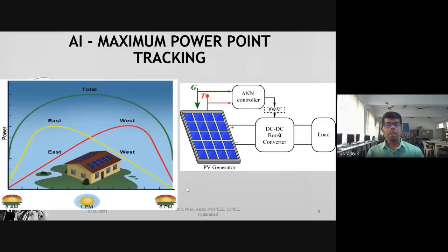That is how you maintain the efficiency at the battery. Here in the PV generator panel, you can take the temperature of the panel, what generation is happening, and what angle it is tilted. Everything has to be communicated to that particular system so that the power generation will be maximum. Then you can use it directly for the load, or convert that DC supply into AC and charge the batteries.